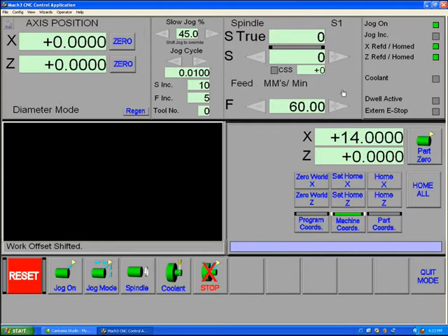Your feed that you've set your machine to is a smart DRO, unlike mill. In this, you select your forward and backward arrows or simply type in a value to be used as a feed rate. This display changes whenever an axis is moving. As you can see, when I jog my Z axis, I'm now displaying 65.3 millimeters per minute. When I release the button, it goes back to displaying what the requested feed rate is for a G-code move.